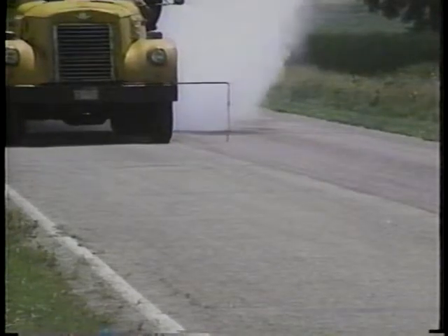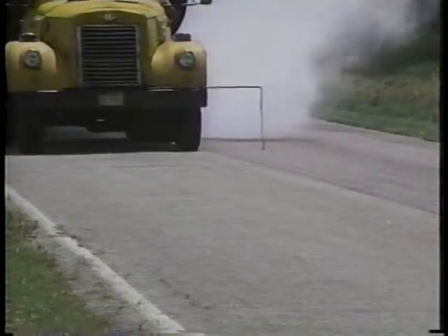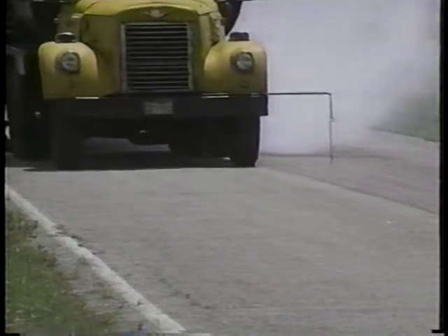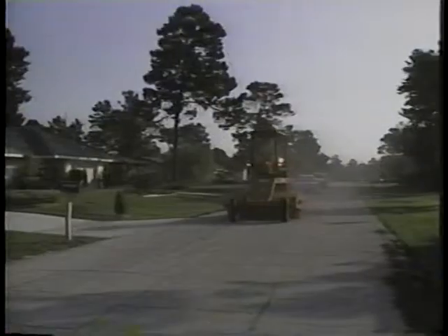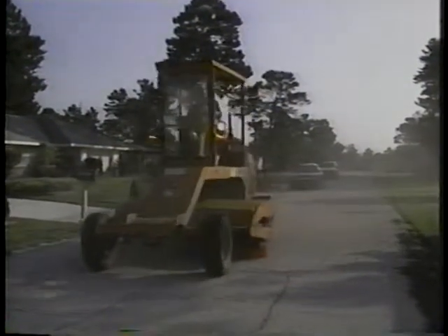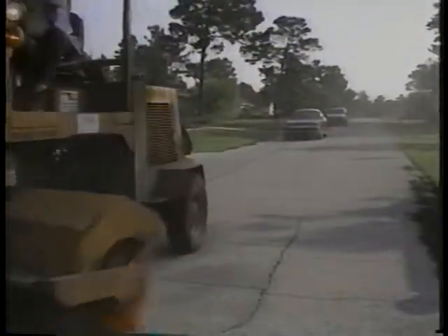On the other hand, chip seals are effective in treating pavements that are raveling and are oxidized and weathered. In all cases, you need to be sure that the existing surface is completely clean before the chip seal is applied. Hardened mud and other foreign matter may not be removable by brooming alone. Washing or other cleaning methods may be needed.